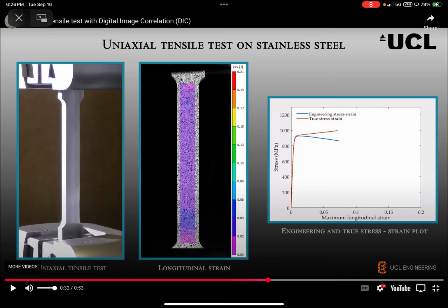So that's the difference between the engineering stress and the true stress. With engineering stress, when we're dealing with it, we generally keep it within this elastic range because it just makes design so much easier. But once you start getting to this point, then you've got a ton of other problems that you've got to deal with, and it's like, why even bother? Just keep our design in here. Our math is going to be good enough, right? The numbers should work.